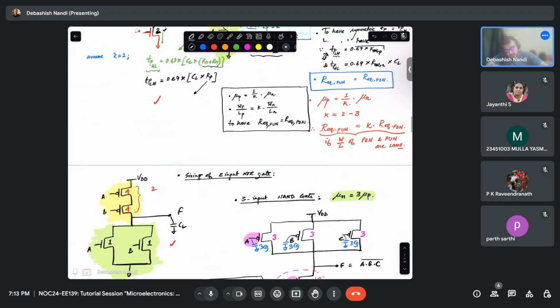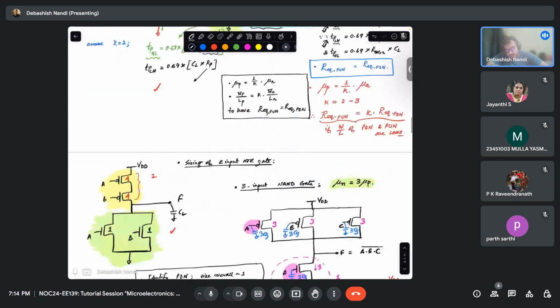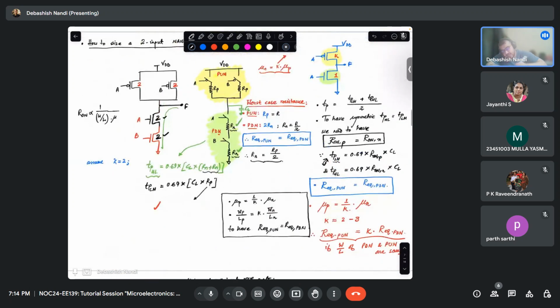Okay. Now quickly can you tell what is the logical effort for this case? So what is C in logic here? C in logic I can see 4CG, and C in inverter is what?